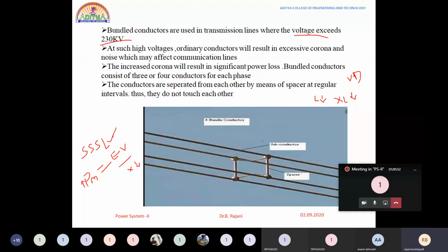That is why in every problem we have come across the double circuit three phase line, single circuit lines, and single phase double circuit line. We have talked like that. What does it mean? In the three phases, each phase comprises four conductors. Subconductors are placed like this. Let us suppose we have taken four conductors. That is called a bundle. Four bundle conductors, and this is the spacing of this.